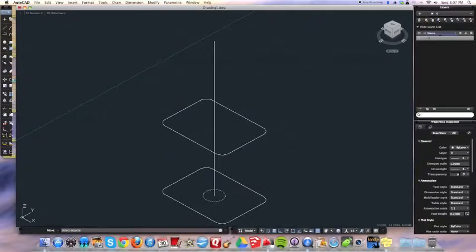Click the circle, enter. I'm going to specify my base point, which is still going to be the center, enter, or click, and I'm just going to start moving up. Now this was at 6, the whole thing is 9, so let's put this at 9 for now because that will be the top. Alright, and we'll do a move copy, a copy down here. We'll copy that, enter, and I'll specify the base point again, click there, and I'll move down let's say 2, enter.